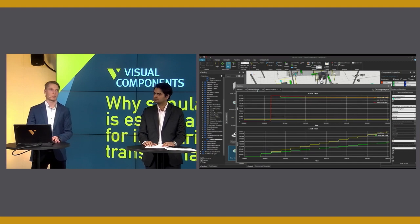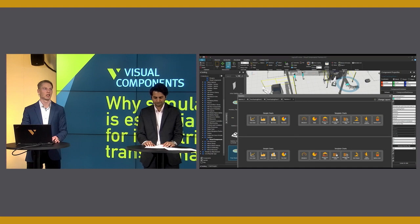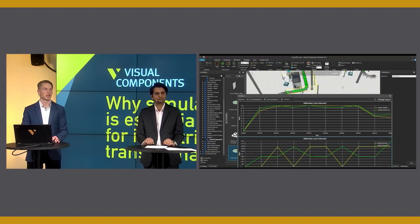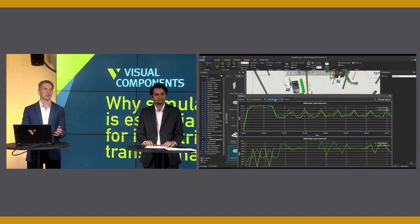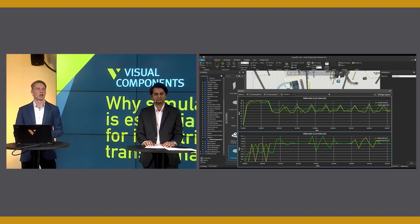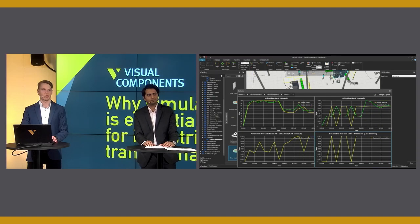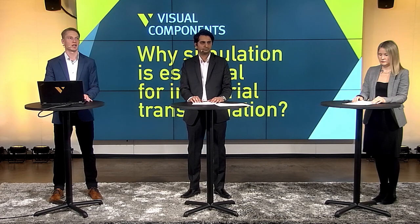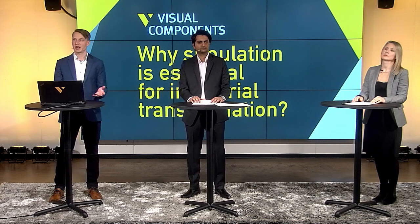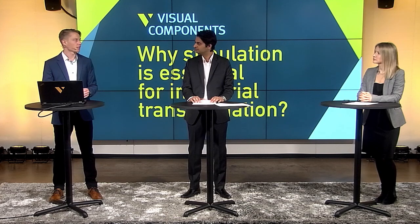We have also some smart helper components that can be used to collect data on passing products and to generate a chart for us, like the time tracking point that measures the cycle time and lead times. Many times the utilization rate of a resource is important, and one of the KPIs to detect bottlenecks. And obviously the same applies to processes like the machines. Any changes made to the layout, like product feed rate, are reflected in the statistics.